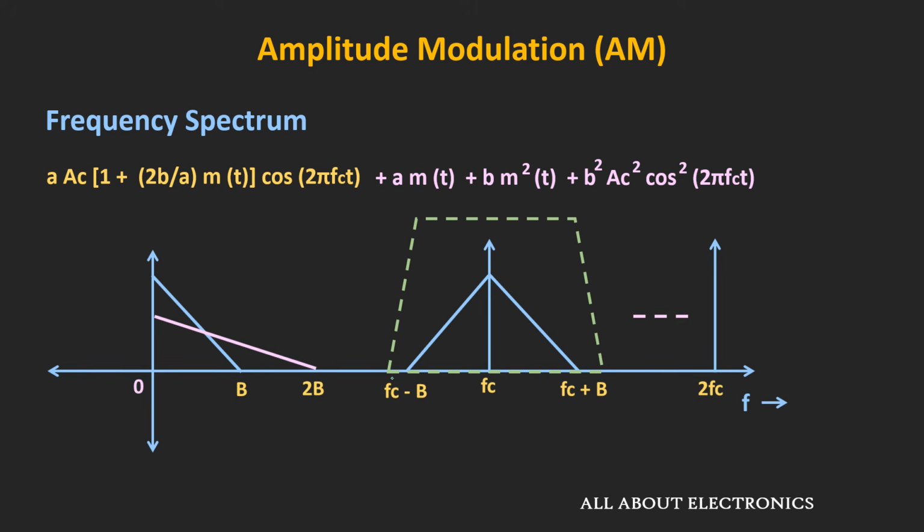So here the bandpass filter should be designed in such a way that its center frequency is around Fc, and the pass band of this bandpass filter should be at least equal to 2B, so that we can filter out the desired spectrum. Apart from that, we also need to make sure that the passband of the filter does not overlap with any other frequencies.